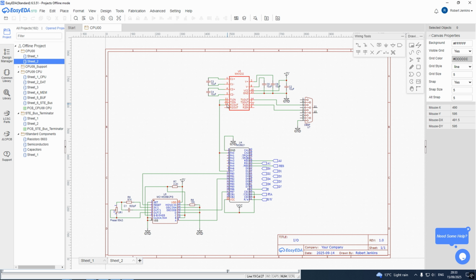And I say it's got an output from the receiver, which would have been a 1489, connected both directly to the transmitter in, which just gives the loop back to the terminal, so it displays what key you've pressed, and it's connected to both an input and an output on the PIA, on A0 and A7.